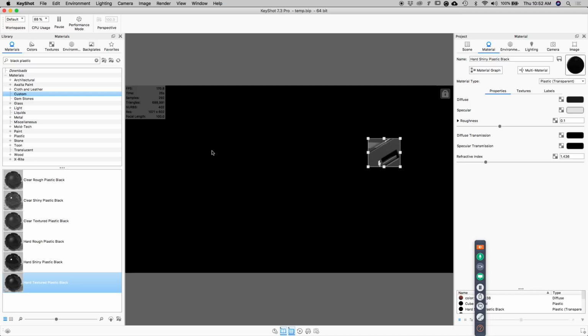And when it looks good enough, I look at the number of samples and then I decide to type that into my samples settings for my final rendering. And that will ensure that the whole image has this quality of resolution. And if I'm left with any hot spots or any fireflies, I can take care of those in post. It's not the end of the world. I'm focused on speed. I want to get in and out instead of tweaking lights and materials forever.